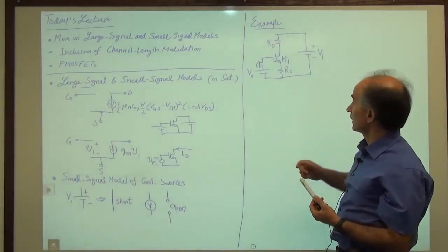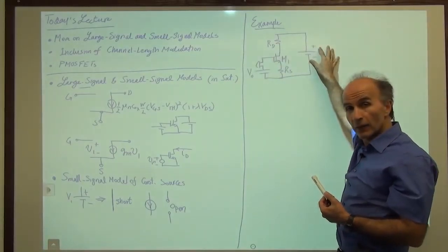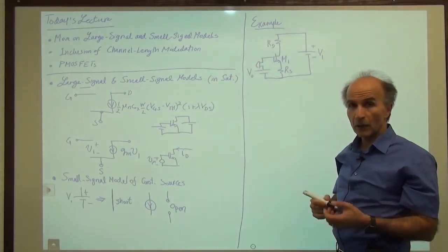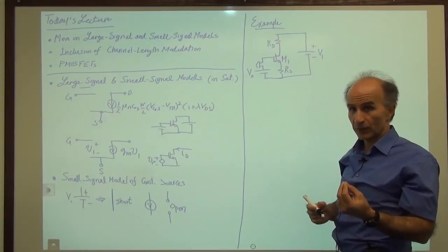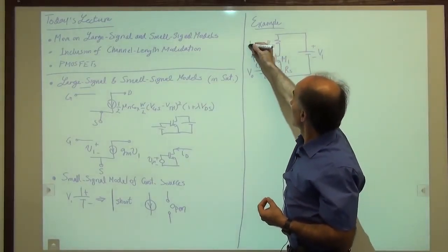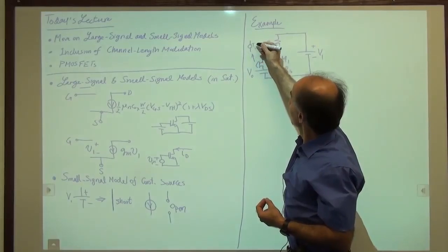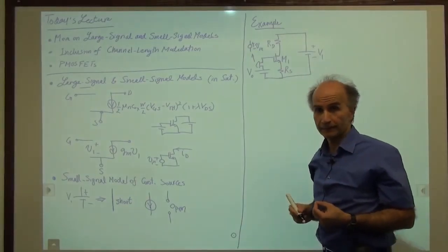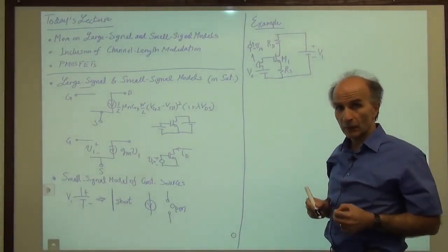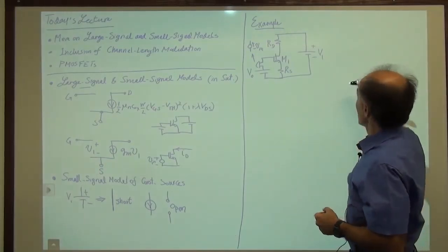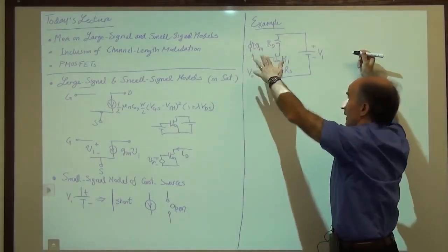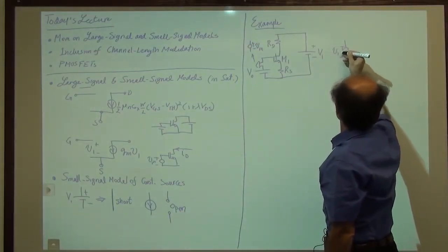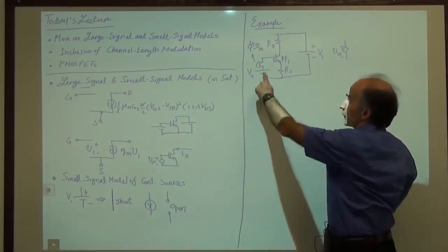Okay, well, we can start from here and make our way towards the right. We model this microphone for now by only a simple time-varying voltage source. So this microphone is just a time-varying voltage source. We may call it Vin with lowercase, again, to indicate small signals. So that is the input voltage source. All right, so we begin with that. Does this change with time? Yes, so it has to stay in the small signal model. So here's the model for that. Now we go to this guy.